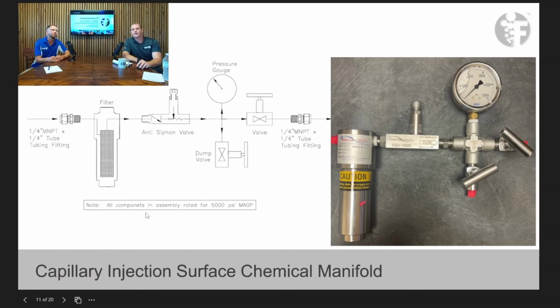This might be a dumb question, but how do you get debris in the fluid that you're pumping? Well, we're going to get to that in a little bit, but typically it happens when filling up totes. So when the chemical company's filling the tank up. Right, they'll stir up stuff from the bottom. Usually that ball valve off of that tank is 2 inches high for a reason.